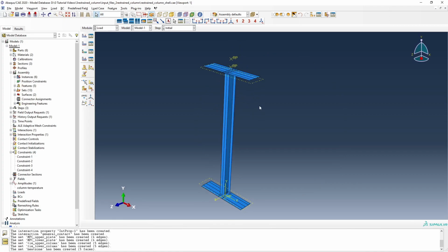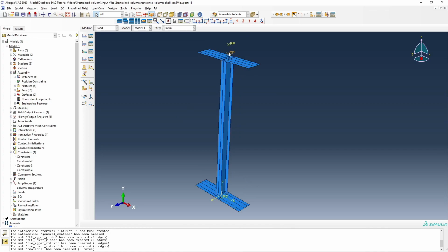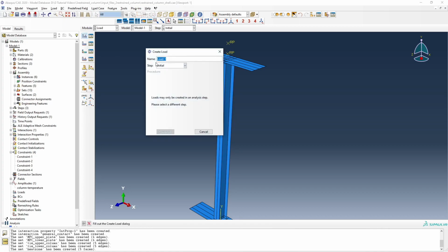So here, and also we can hide this datum. So let's hide these datums. So we can select this one hide and also select this one hide. So the datums are hidden, and then let's cancel the procedures, and now we will first create the load, and the load is applied here in this first discrete point in our case. So let's go and create the load, and let's name it the mechanical loading, and then the concentrated type force.